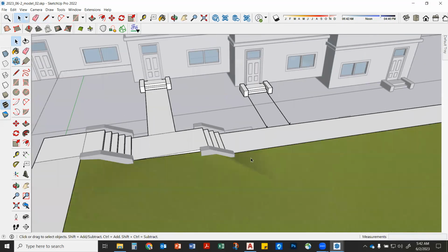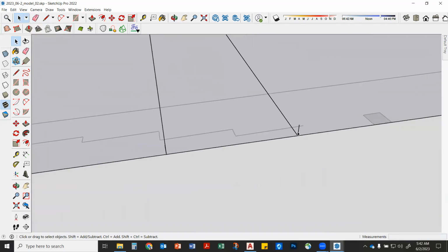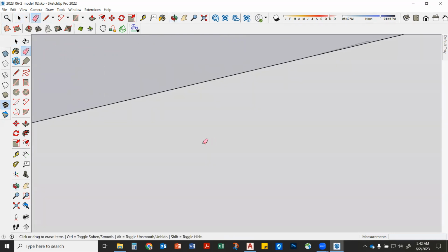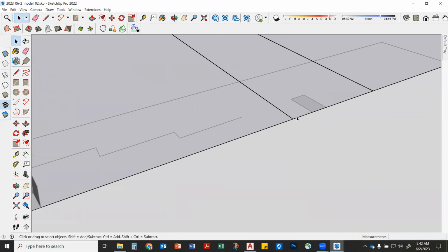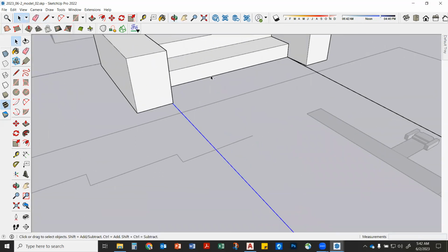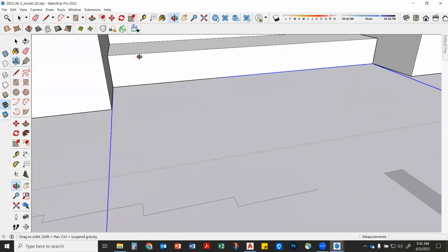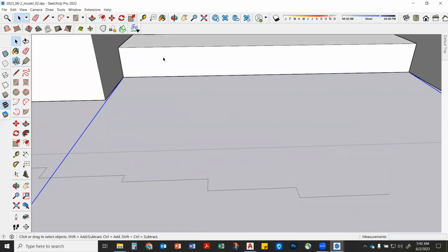Just like we did when we made this tin in here. All we had to do is make sure we had an outline, yeah? I don't need these little straight up lines either because we found those locations. So I can erase those. Select this. Select this. Select this. I'm holding down Control, right? And remember, this one might be hard to see. So I try to move the view a little bit and you can actually see it flashing blue, right? So I have that line. There's two lines there, which is why it's hard to see if I got it.